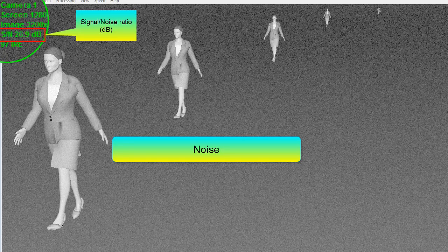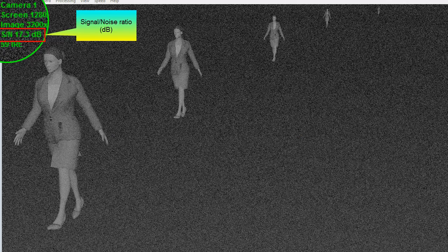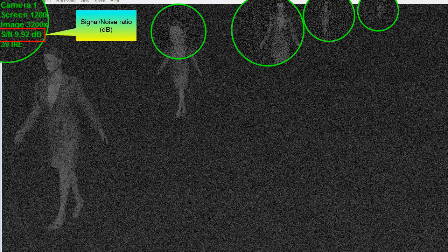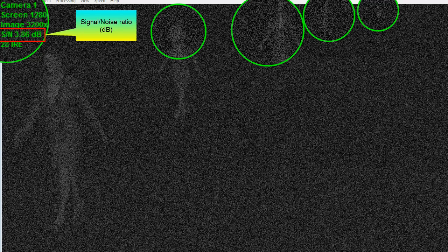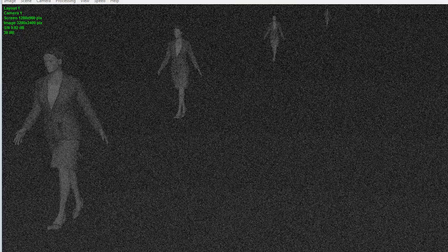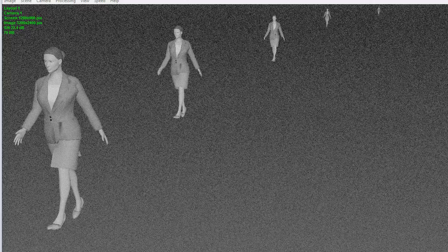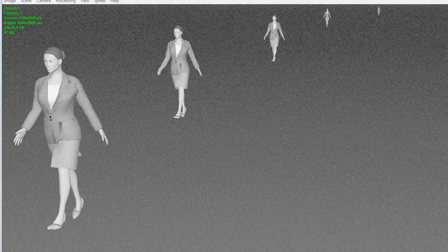Noise. Under low light conditions on the scene, on the image, the contrast decreases and noise increases. Noise hinders detection or identification of a target when the noise becomes comparable to the contrast of the target. A little noise does not greatly interfere with detection of high contrast targets, but it hides targets of low contrast.